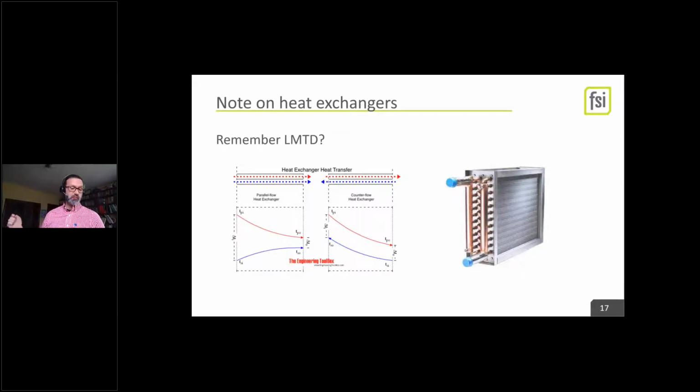So turning the loop temperature down, yes, you can. You don't really get any benefit if you're a conventional boiler, but on a heat pump basis, yes, we definitely want to talk about that. And of course, when we used condensing boilers, we would run 180 degrees on the coldest days and then turn them back down slowly, depending on the temperature of the day. We'd ramp them back down to 140, 135 on the warmer days of the year to get the peak efficiency. The main limitation to doing that is right here.